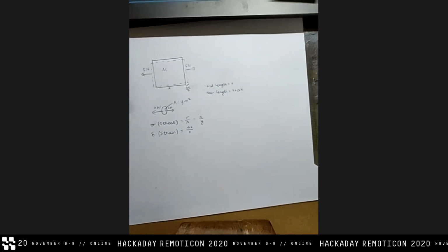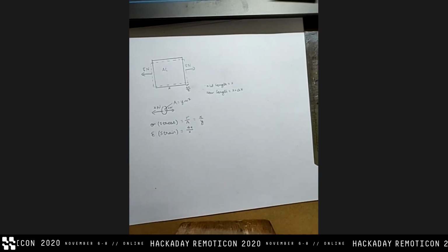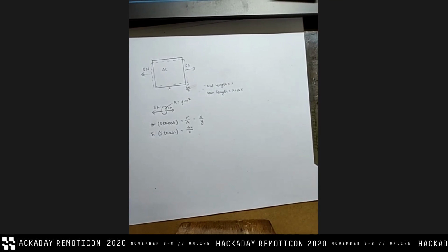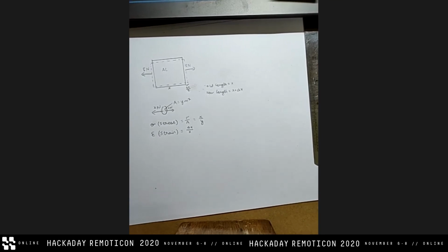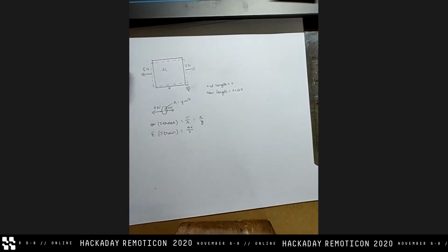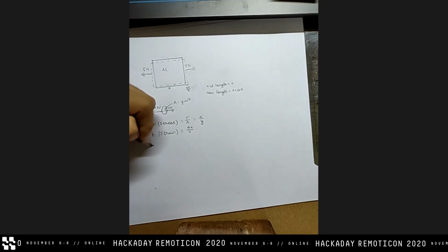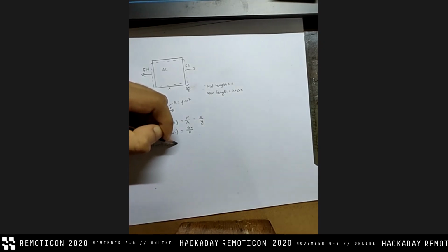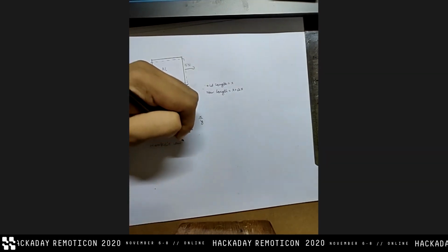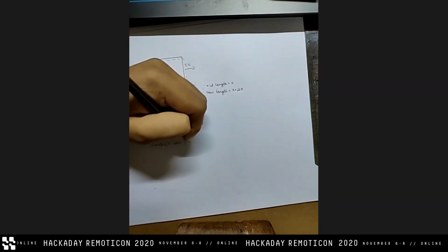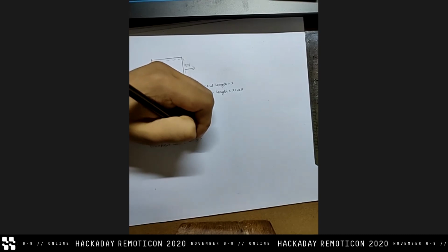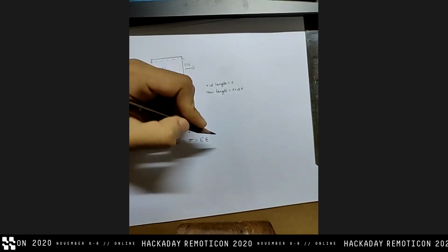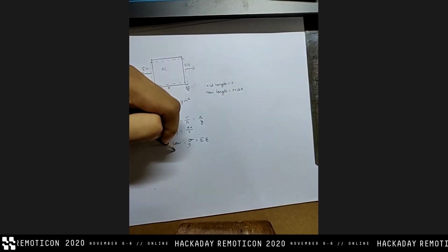Now this is useful, but with a simulation, you only know the forces. You don't know the effect of the forces. If you knew the effect, why would you be doing the simulation? That's a waste of time. So there's a relationship between stress and strain, and that's Hooke's law. And that is that your stress is equal to Young's modulus times strain. Let me just label this nicely.